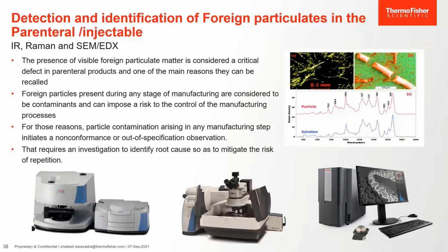Intrinsic particles could originate from the medicinal product or API itself. They are undesirable, but may be part of the medicinal product and described in authorization. However, extrinsic particles or foreign particles originating from outside, such as fibers, glass, abrasion of machine parts, are undesired under any circumstances.